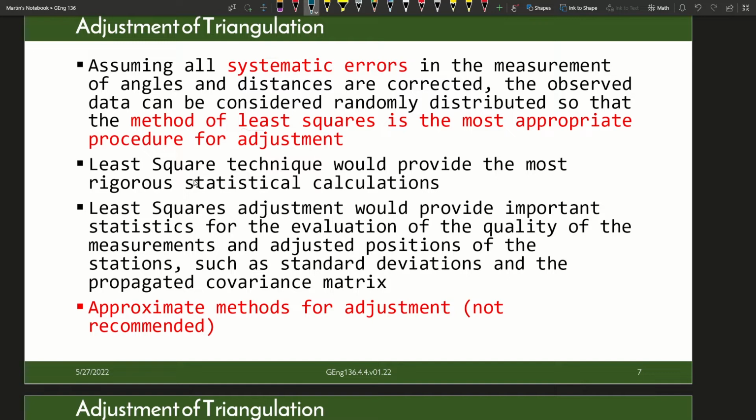So you can also evaluate your adjustments before and after the adjustment, given that the error is acceptable at that point. Once you have adjusted the triangulation system, check the statistics, and these will tell you how good or how bad the results are.